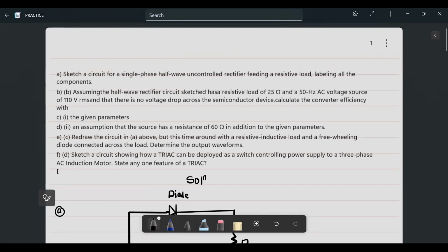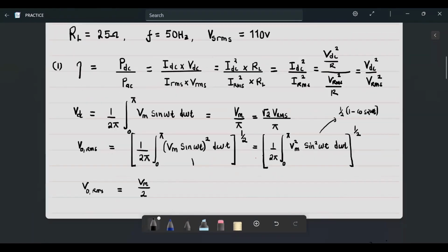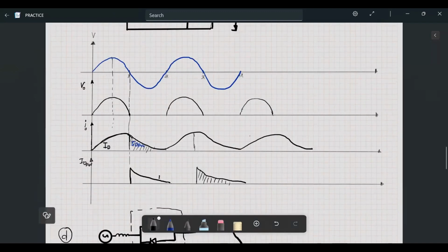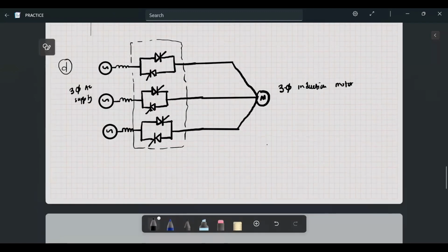So what happens is that the thyristor can handle both polarities, positive and negative. When the polarity is positive applied, you know where it's going to be directed. If this polarity is positive, you notice that this thyristor is not in conduction. So let's say we apply positive, positive, positive. It means that the three thyristors on top are the ones that will be in conduction, right? And then apply negative, negative, negative. You notice that the other three thyristors now will be in conduction.